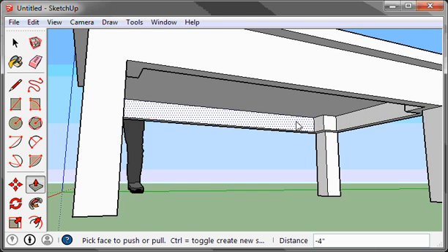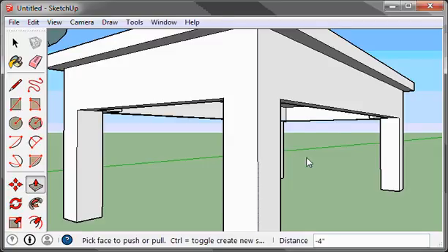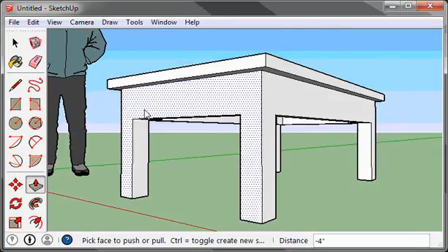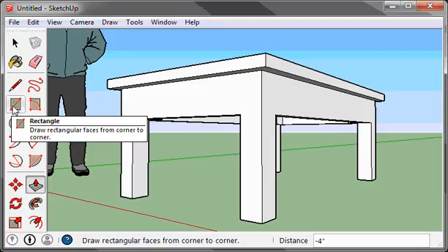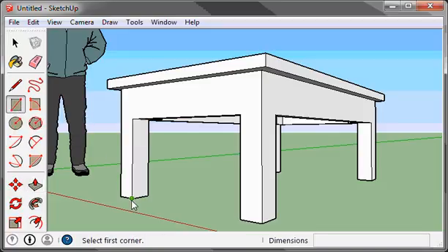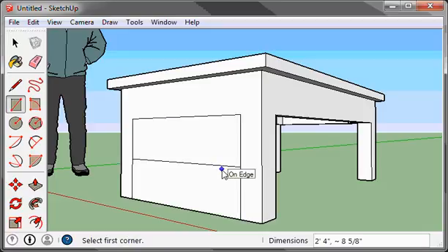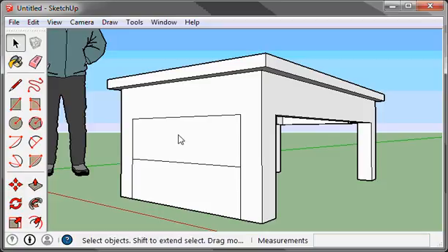Now we're going to make a shelf for the bottom of the table. There are absolutely a couple of ways to do this, but one of the easiest is to use the rectangle tool here in order to draw a shape across 2 of the legs of our table. You could even go up to exactly the midpoint, which it'll snap to, turn that blue color and say the word midpoint. When you do that, it's going to fill in not just the top, but also the bottom of this new shape. You can use the select tool in order to select the top part and press the delete key on the keyboard to get back that open shape.